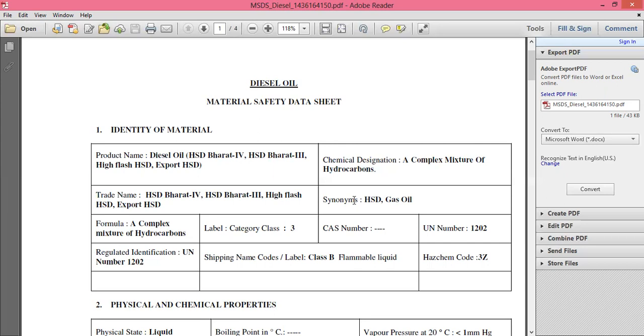Now, understand this very carefully: please go through this MSDS before handling whatever small quantity of chemical you are handling. Wear the appropriate PPE. Even if you have to spend some of your valuable time to read this MSDS, please do it. It is better to keep yourself and your other crew members safe rather than being sorry at a later stage.